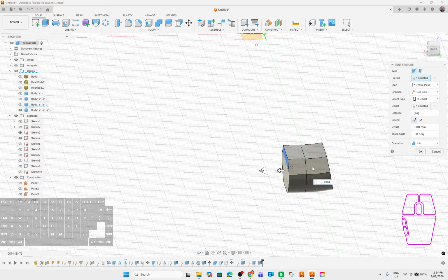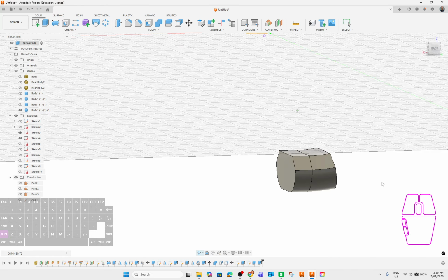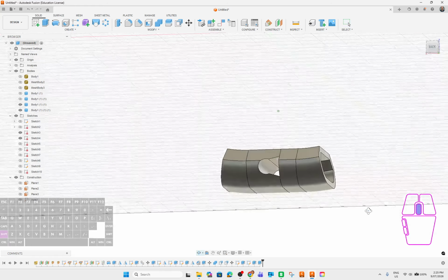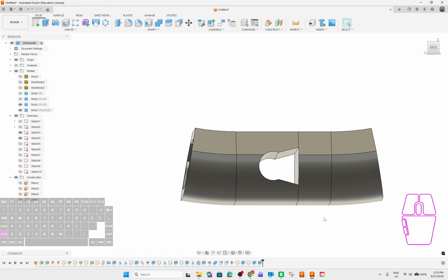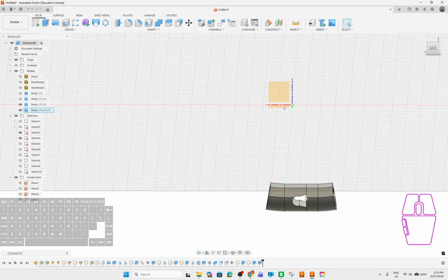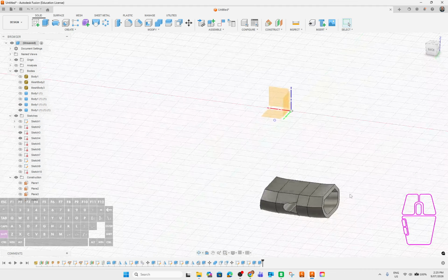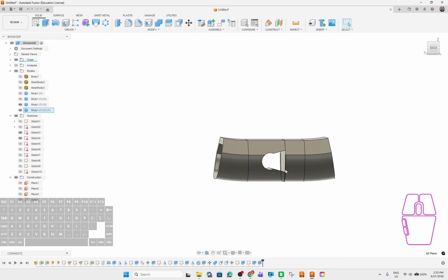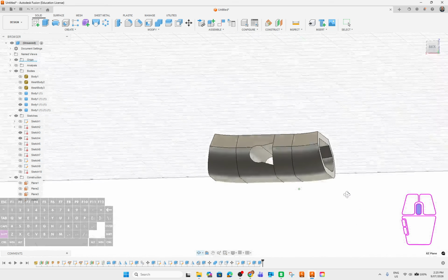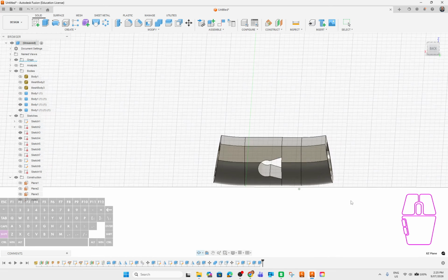Yeah, make that invisible and then go OK. That should work, because I wouldn't need these butting up against each other. Good, and then I'm going to add another sketch, and pretty much fill that in and leave a bit of a gap, and that will be our clasp for this particular iteration. It may not work, but it's just something we can start with and refine from there. We'd print this as two separate bodies. Happy days. So let's go in and do that.